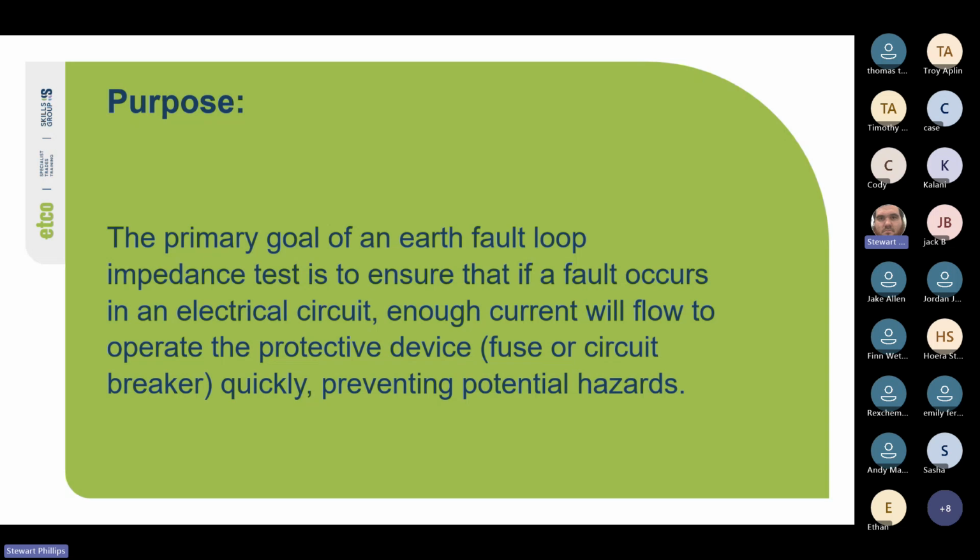They do have a set reading they have to achieve, but again, each situation is going to be different. But yeah, distance does play a role in it, as well as soil type. So if you've got really sandy soil and it's dry, it's not a very good conductor. Whereas if you've got kind of wet, normal dirt or mud, it works better, which is actually why they used to put the earth stake outside the house where the garden tap was, because the idea was that you'd leave the garden tap on slightly and the water would continuously wet the ground, and so you'd have a better conductive path through the ground.